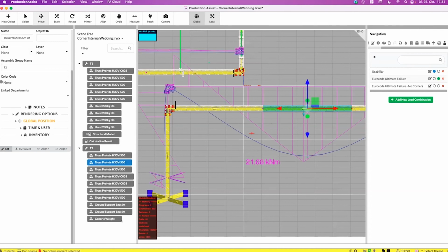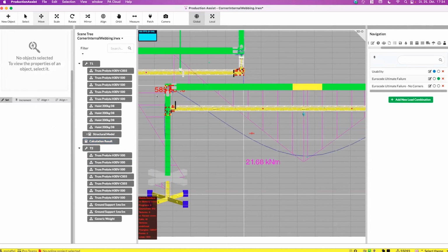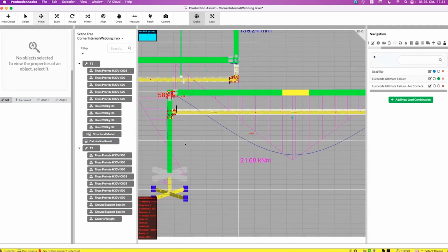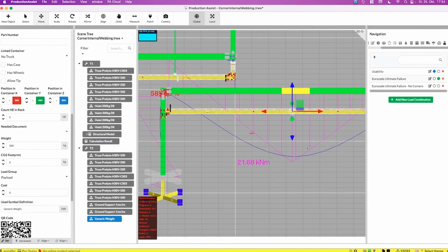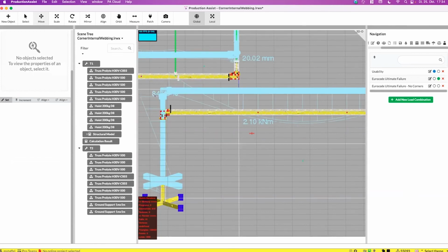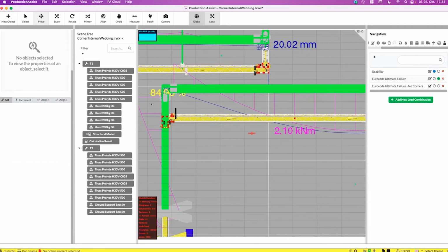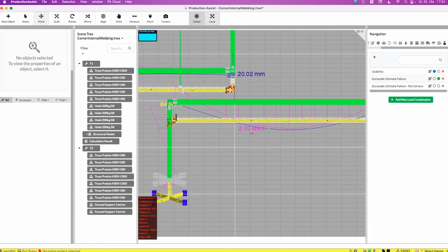If you now look into the workload in here, you actually see that the truss is overloaded. So it's about 600% workload. So in this case, if you do this specific setup, then you will break this. We have in the middle a generic weight, which is about 500 kilos for this span in here. If I'm deleting this, the system with only its own load is still at 85% workload. So the assumption of the corners and the right calculation of this is pretty important for our calculations to have in mind. Okay, thank you very much for this.